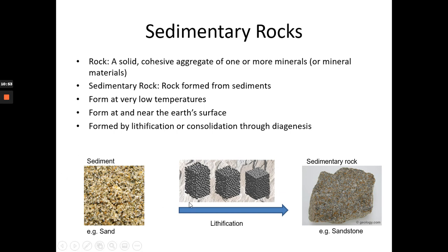Through the process of lithification, which includes things like mechanical compaction, and just put weight from more and more sediment from the top here, resulting in the deposit becoming more and more compact, right? They become closer and closer together, right? The particles. And also with diagenetic processes like cementation, because of water flowing through the pores in between the particles, can result in cement gluing the grains together, right? So you can transform sand to sandstone, for example.